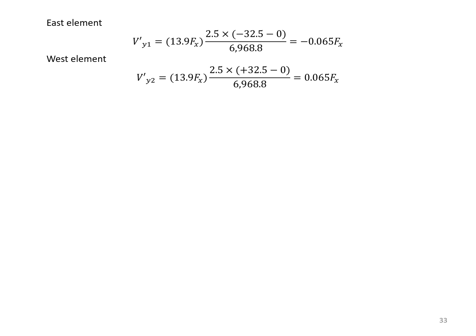Now, of course, the force in the x direction would still have some effect on the east and west elements. So those are according to, again, our similar MC over I equation, right? So denominator, remember that from previous calculations. Corresponding rigidities, corresponding distances with the sign carried out. The total moment is the moment created by Fx. So one is a negative 0.065 Fx, the other one is positive. Always some of these would end up with 0.